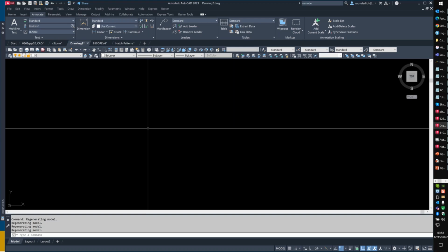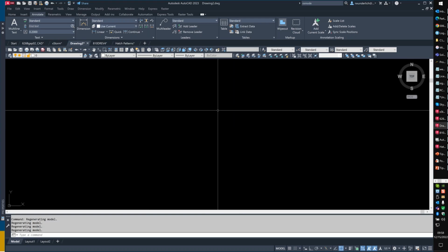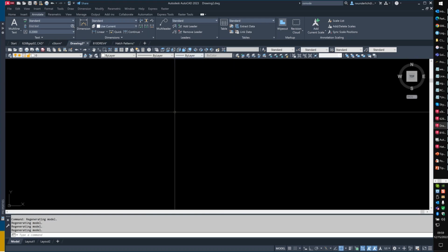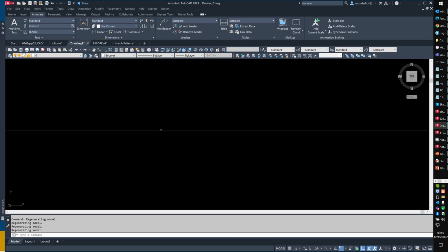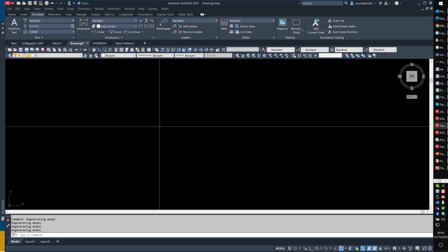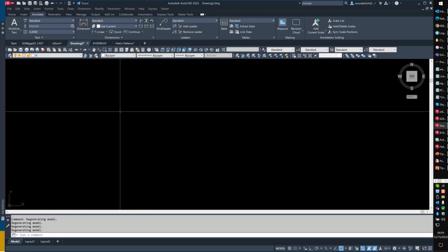I have one machine that is what I consider to be my golden image, and then you create a shortcut to export those settings. You install Civil 3D on the new machine, run it once, close it, import that saved settings zip file, and boom, it's exactly the same as your golden image.